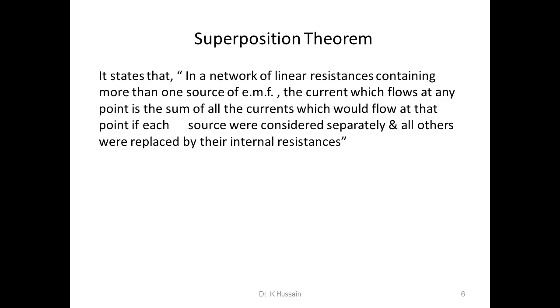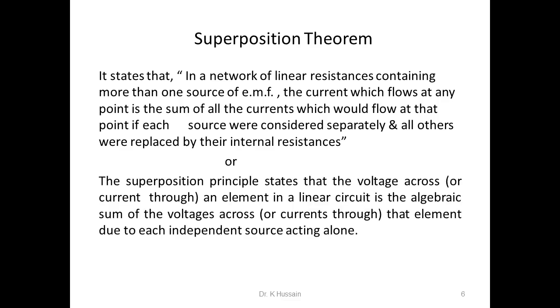In the same theorem, we can use another alternate statement. You can understand easily that both are the same, only in a simpler manner. The superposition principle or theorem states that the voltage across or current through an element in a linear circuit is the algebraic sum of the voltages across that element or currents through that element due to each independent source acting alone.